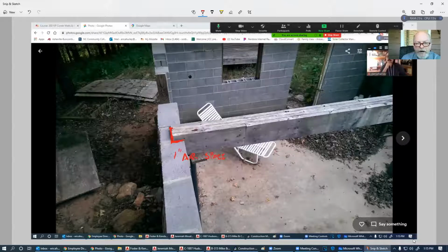Now, in this picture here, I want you to take another gander at something. A beam or a girder takes weight from a point here to a point here, and it wants to support it through the clear span. Look where that joint is. Look where that joint is. You can't put joints in the middle of a free span.